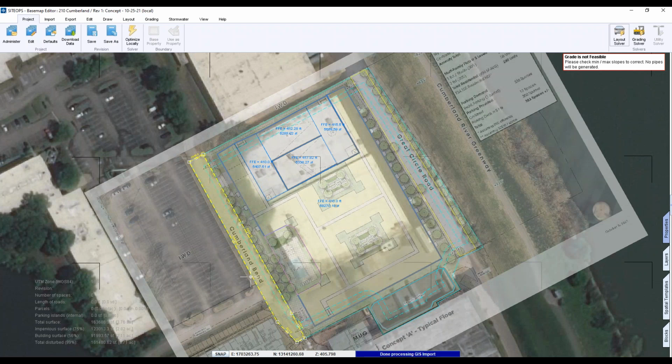We want to be more fast than exact because approximate is absolutely good enough. The main thing to watch is the things that will cause grading problems, such as overlaps. You do have to watch your overlaps a little bit because it'll throw the program off, so be careful in certain situations like that. But if you're not close to an overlap, then it's not really a huge deal.